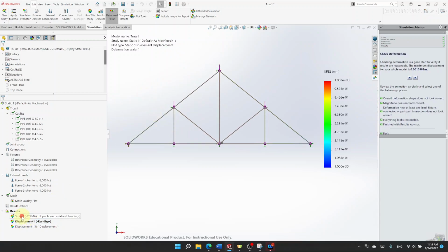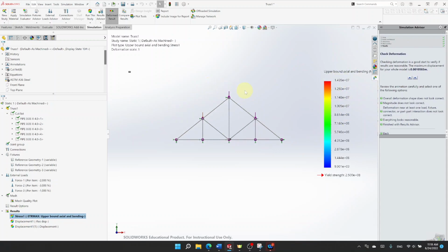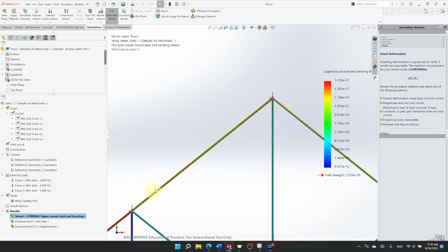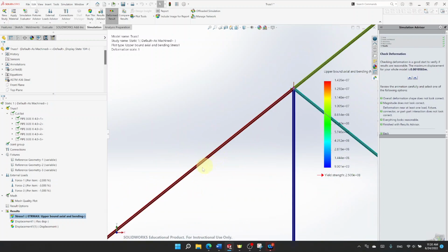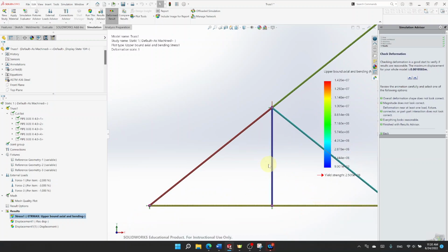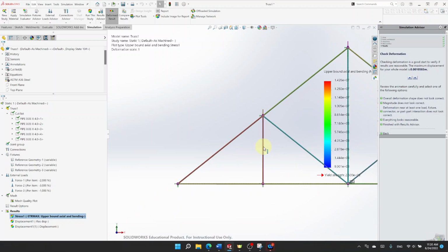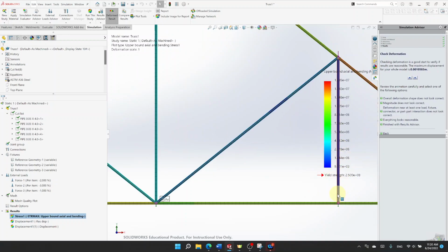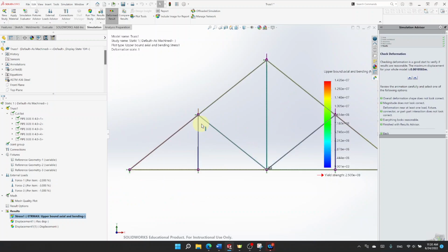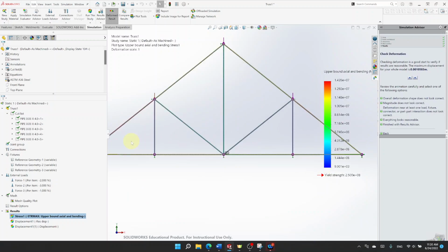Let's click on the stresses. What we can see there is the stress in the different components. And what we want is the same stress in this member from the beginning to the end. Remember, if we cut at any spot on this one, it will be the same. This one is the same color all the way, and it's almost blue. Why are these almost blue? Look at both sides, it's almost blue. Does that make sense for you? I'll let you think about that.